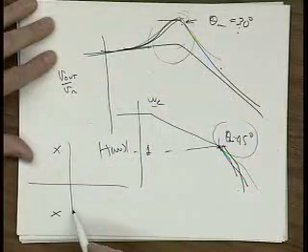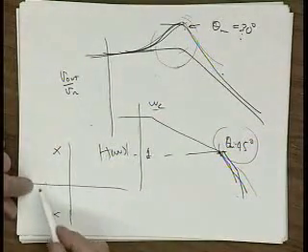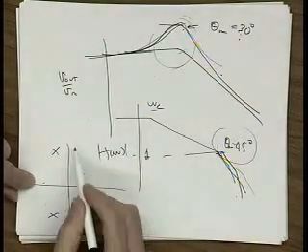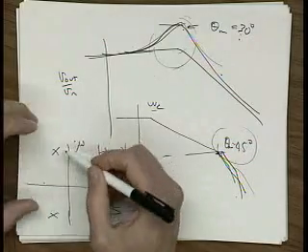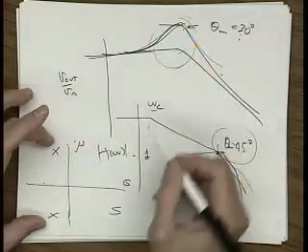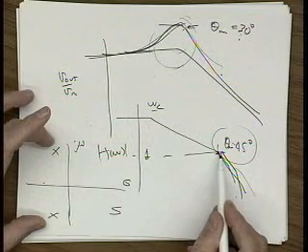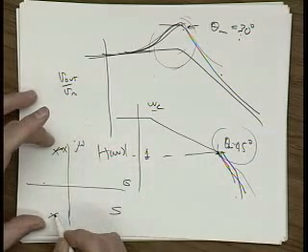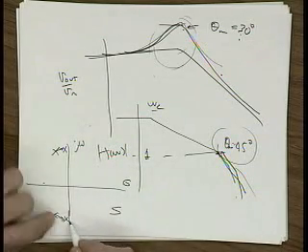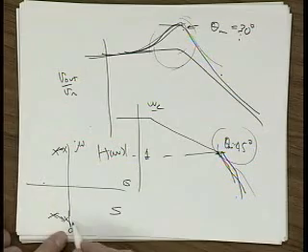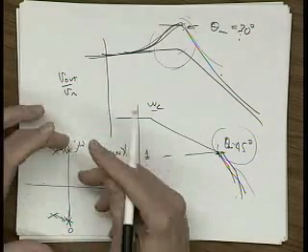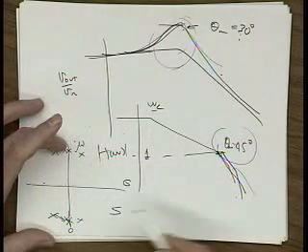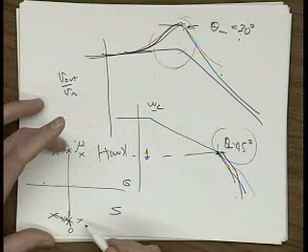After we close the loop, these poles were on the real axis. So this is the S-plane, right? This is j omega, this is sigma. What's really happening as we have less phase margin, if we look at the pole location, as the phase margin gets smaller, these poles are moving towards the axis. In fact, when you have 0 degrees phase margin, the poles are right on the axis, and that's an oscillator. If the poles move over into the right half plane, where you have negative phase margin, the thing's oscillating. Okay?